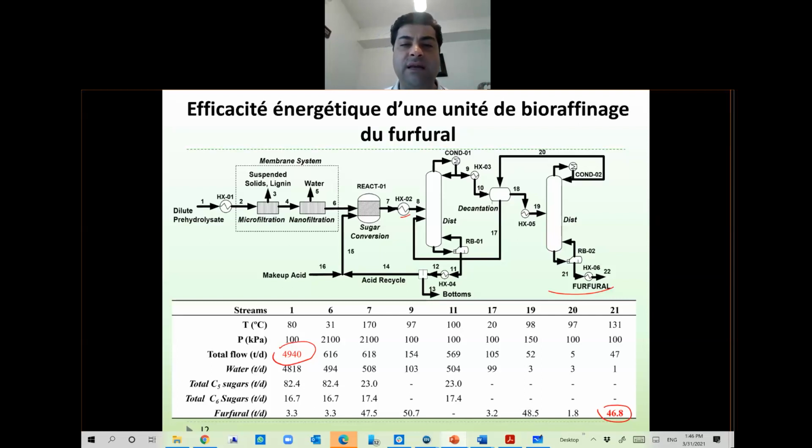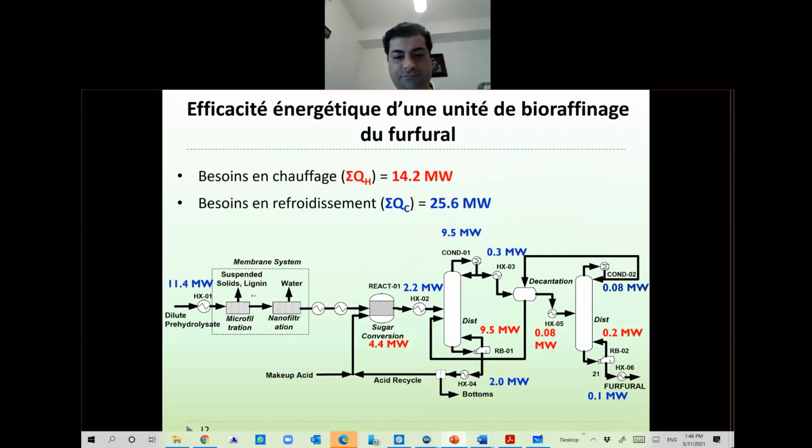This process, if you see in here, after process simulation, for example by Aspen, we figured out that there are some parts of the process that have streams that require energy. We can show them by red color. So these are heat sink streams.